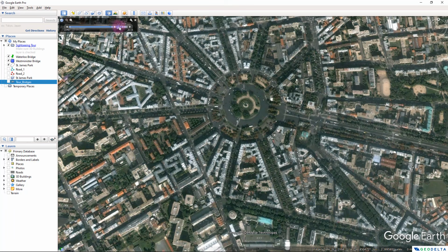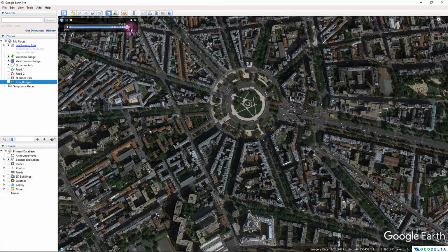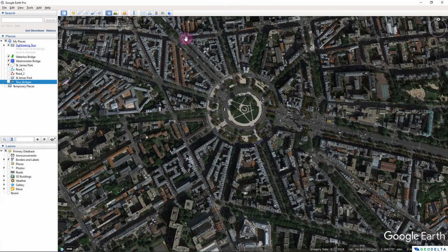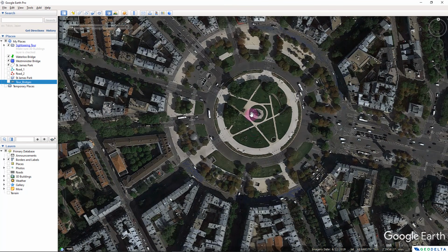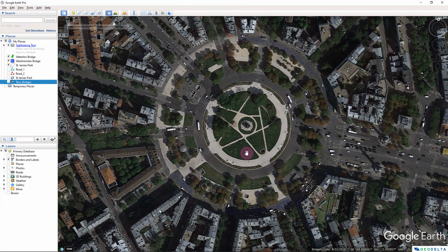And if I slide this back to 2019, the most recent image that we have is of 2019 in the month of August. You can do all sorts of analysis if you look through the details carefully by using this show historical images tool, which can be quite helpful in certain cases, especially when you're analyzing the changes in the land use and land cover over the past few years. And when you're doing stuff like that, this tool can definitely be of immense help without a doubt.